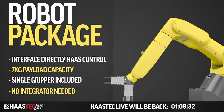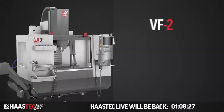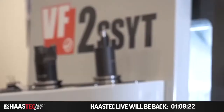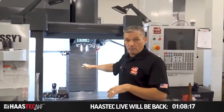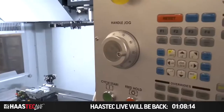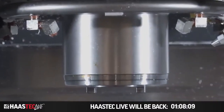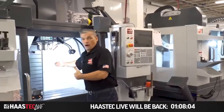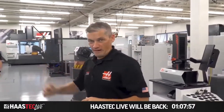Moving on, let's go over here to this VF2 SSYT. The VF2, of course, is one of our best sellers, our small footprint VMC. But this is the Super Speed Y variation. Super Speed, of course, gives you faster rapids and cutting speeds, 1,400 inch per minute rapids, 12K spindle, 30 pocket Super Speed tool changer, and then in this case, the Y option gives you additional Y-axis travel for a deeper work envelope this way. All right, that pretty much wraps it up here for the VF2 SSYT. Let's throw it over to Brian.